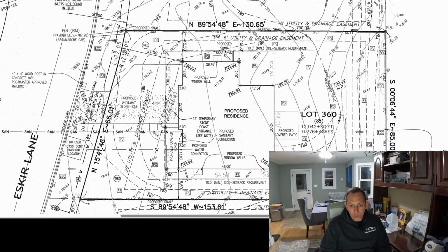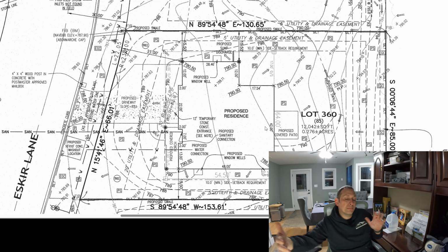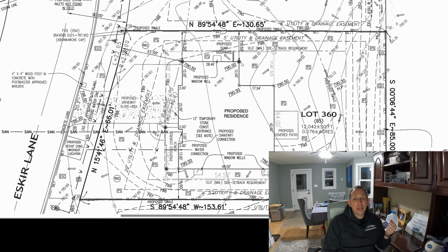But these 4 corners are critically important to locating your foundation and making sure the house isn't twisted on the lot. And the other thing it helps you do is avoid accidentally building the house in an easement or within a required setback, right? We're required a 10-foot minimum setback. You'll see we have 15 and a half feet on this house, so we have wiggle room. Sometimes you only have like 3 inches of wiggle room, and you gotta make sure you hit it, and that's where these corners come in critical, so you have your exact locations.